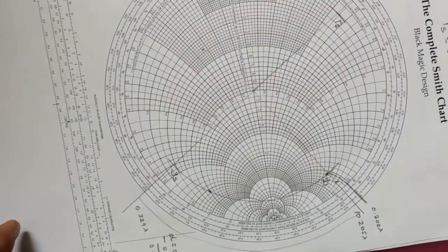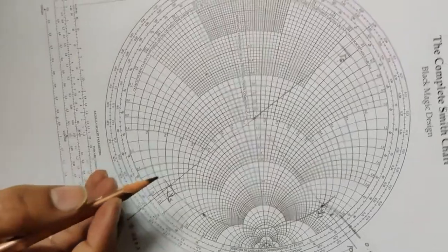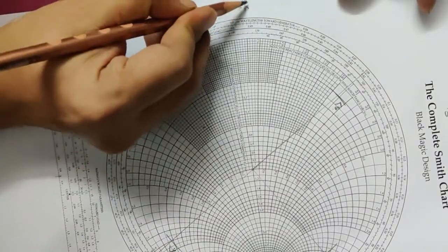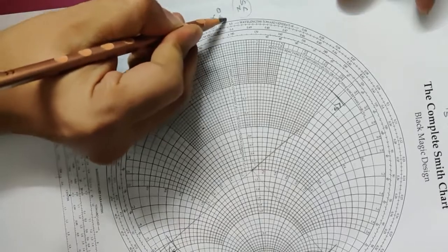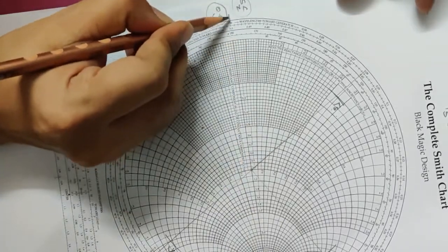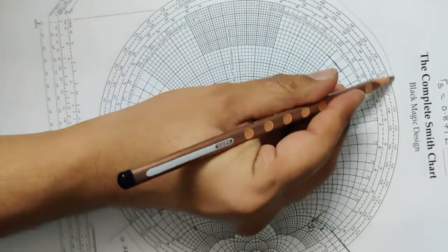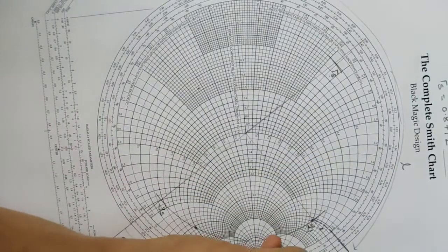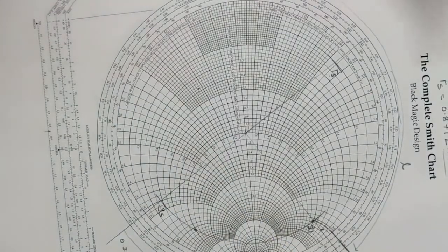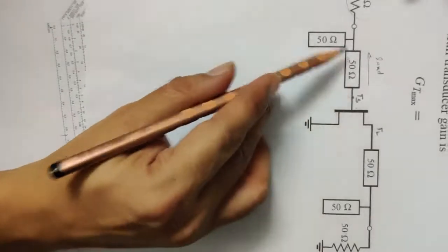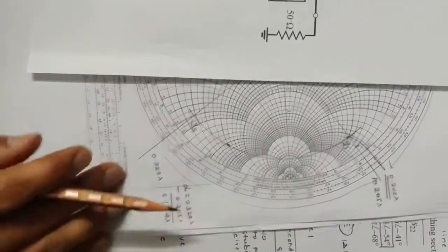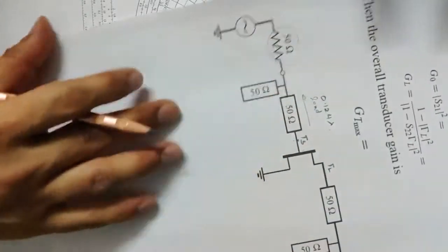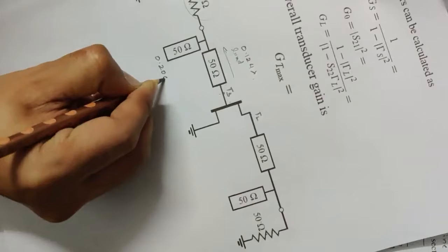Now we are designing open circuited stub in Y. So as you know, this point is short circuited in Z. So this is short circuited point in Z. Similarly, the same point is nothing but open circuited in Y. So one has to always measure the length from this end up to this point. And this is nothing but the length of this stub. And length of this stub turns out to be 0.200 lambda. So if you consider this design, we have calculated the distance of the stub as 0.124 lambda and the length of the stub as 0.200 lambda.